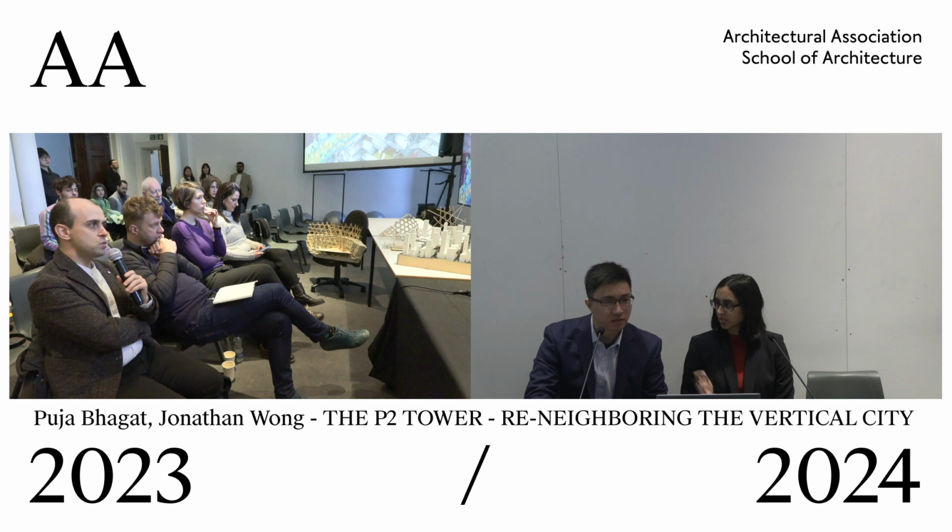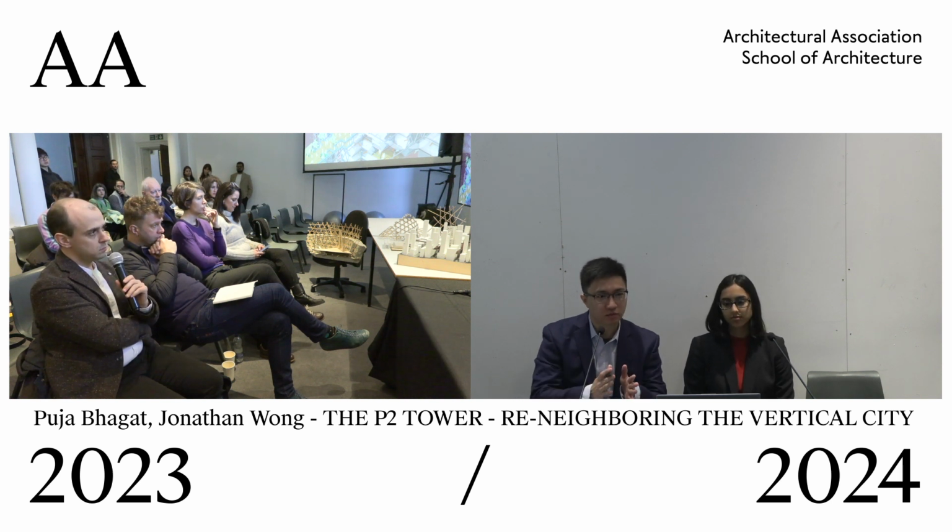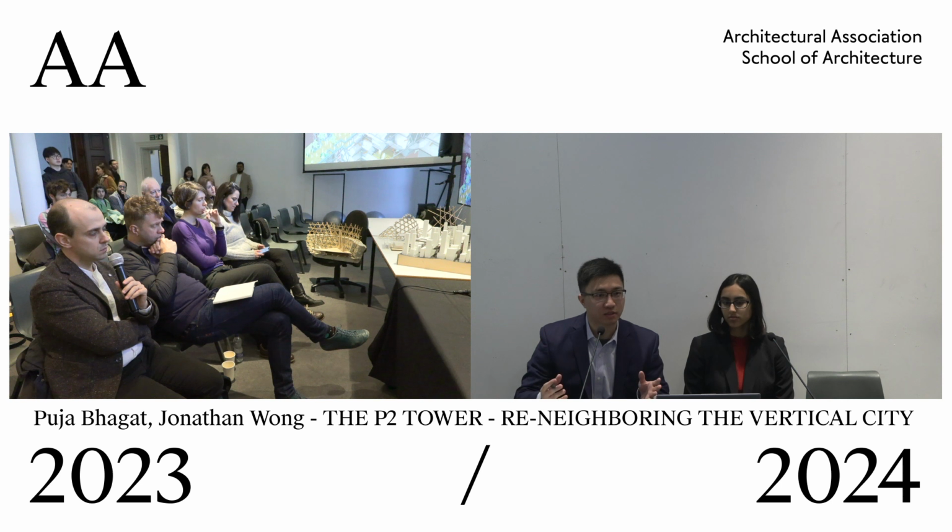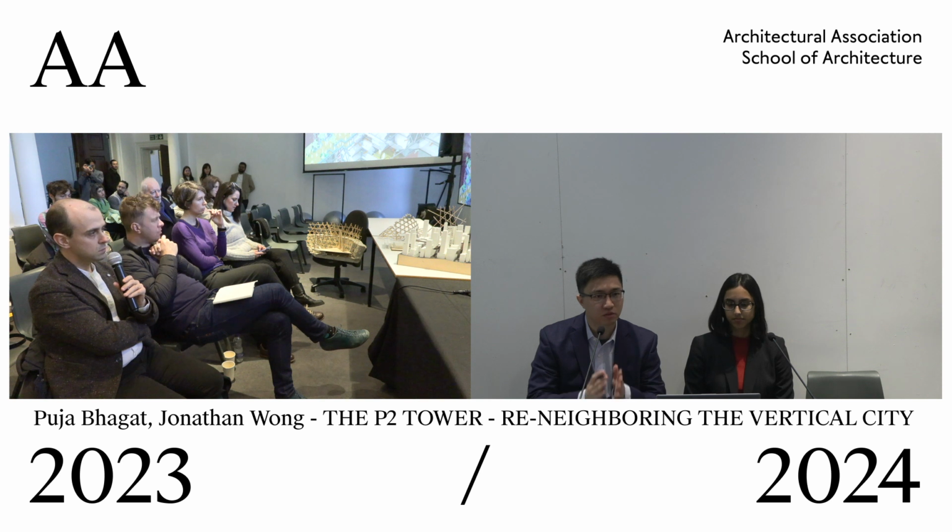Yeah, so the idea with the vertical circulation in the tower is to remove that traditional idea of a central core for transportation. That's why we use an exoskeleton to transfer all the loads to the outside of the tower, and then that third transitional space that we discussed previously weaves vertically throughout the tower, and that's where the main source of circulation would be.